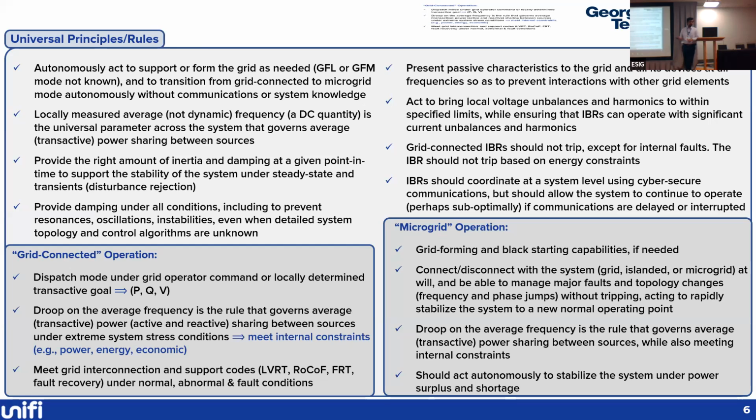inverter resources. We've spoken about damping and we've spoken about inertia, both from the tutorial that we had and from the other presentations that we had. One of the things that we wanted to showcase is that the inverter should present a passive characteristic to the entire system. Now, this is more of a frequency domain criterion, in that, looking at the various frequencies across which the inverter controls operate, looking at the bandwidth of the inverter controls, it should essentially present a passive characteristic to the system so that you can go towards a more globalized stability criterion, which can be achieved with grid forming inverters.